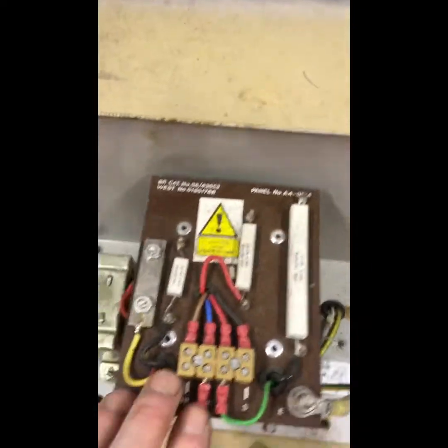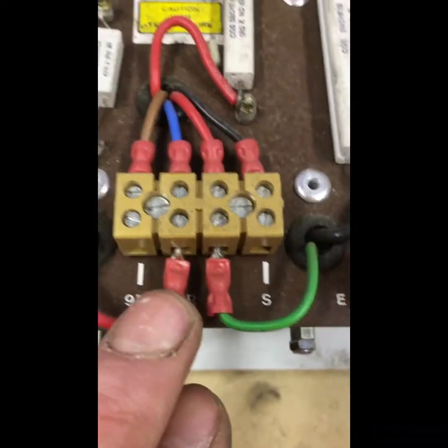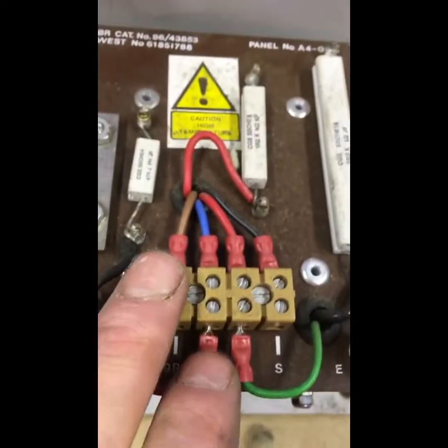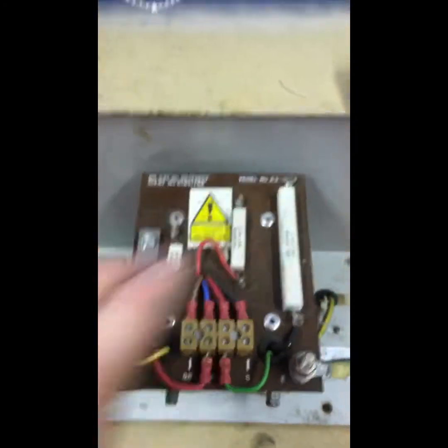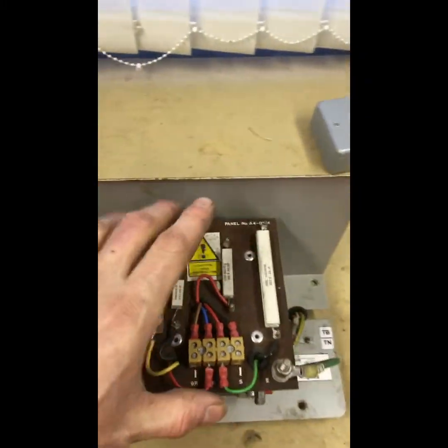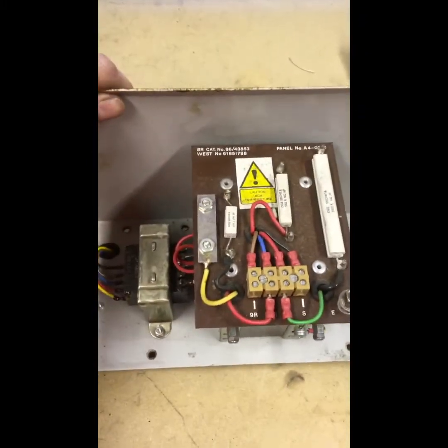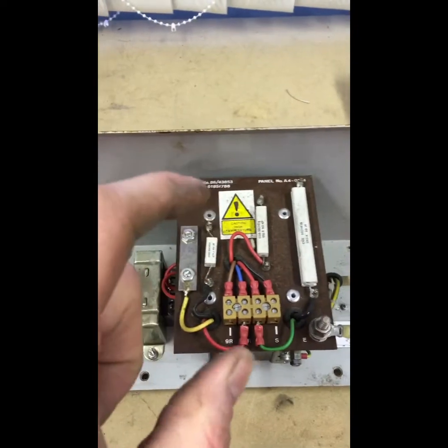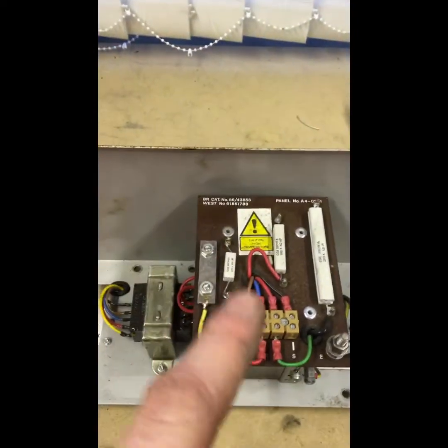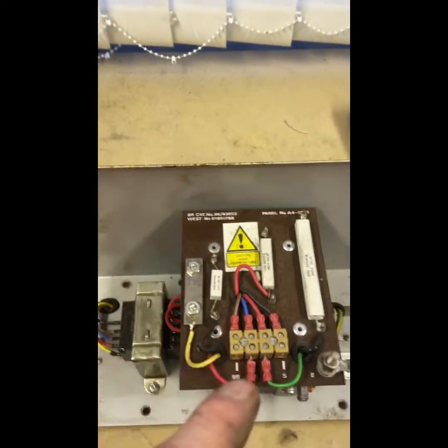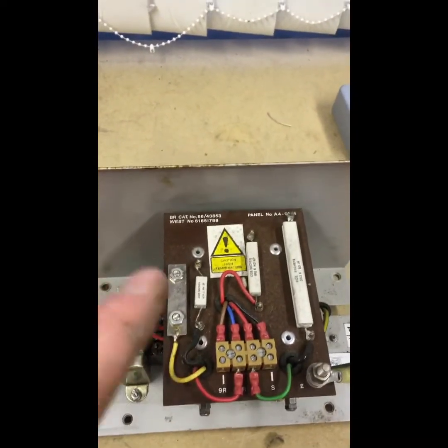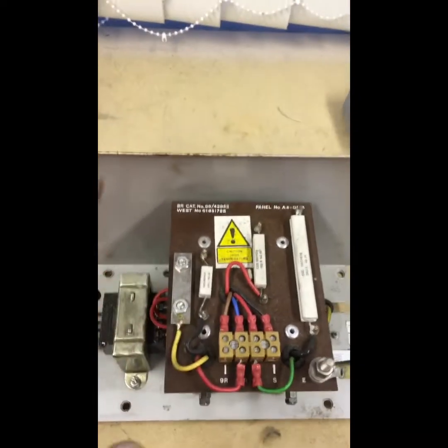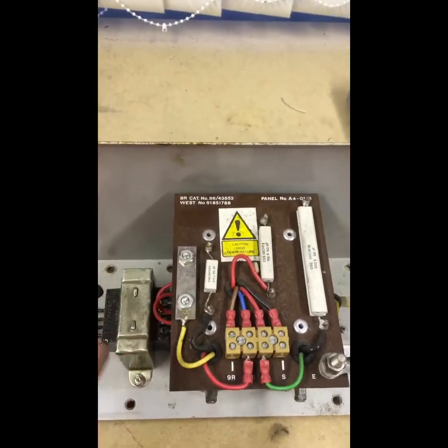What we also have, as you can see, is we can set it for 9 or 20 ohm resistance, and also long and short tracks. They kick out around about 67 volts, so they're quite high power. AC immune, so if you're going to use this, you need to match it with the correct relay. It has been known for these to be run with shelf type track relays before, but with extra resistances in. It depends on what your Heritage Railway has available and what you're using.